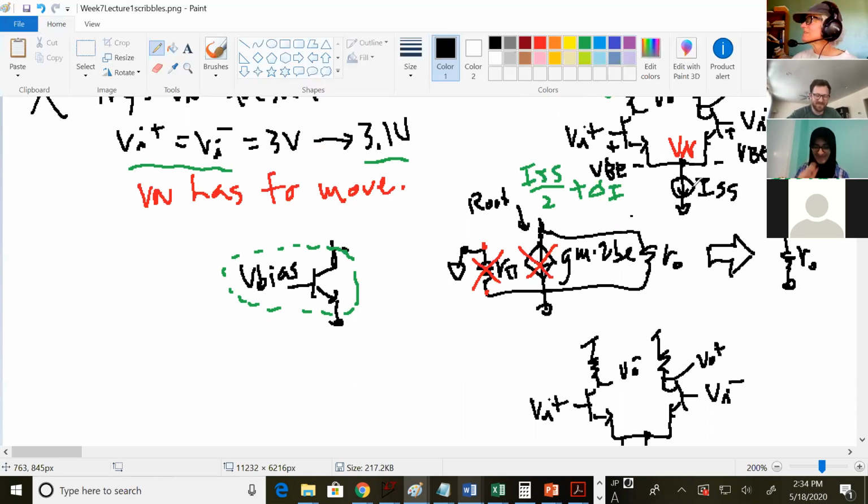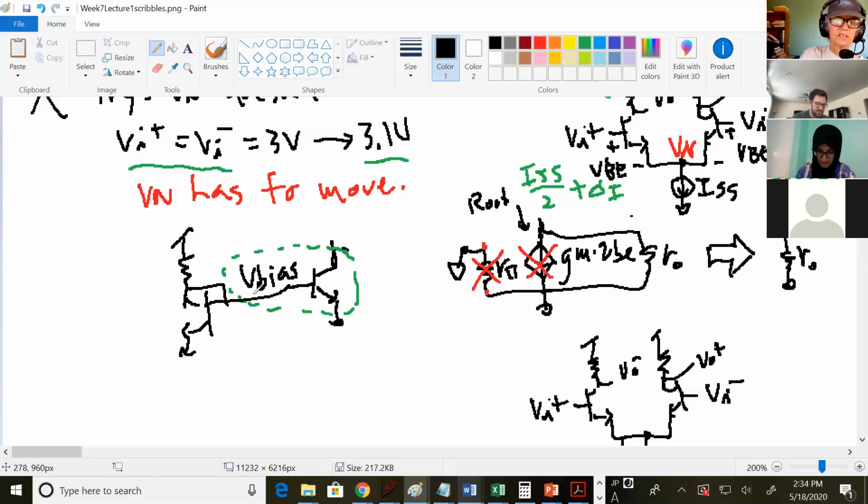If you see a current source, that in a real circuit would be replaced with a current mirror. Oh, right. So this is just saying, let's take that one step, de-abstract it and turn it into the actual circuitry that would go there. Okay. And that would be a transistor with the biasing circuitry. And this is a DC voltage right here.